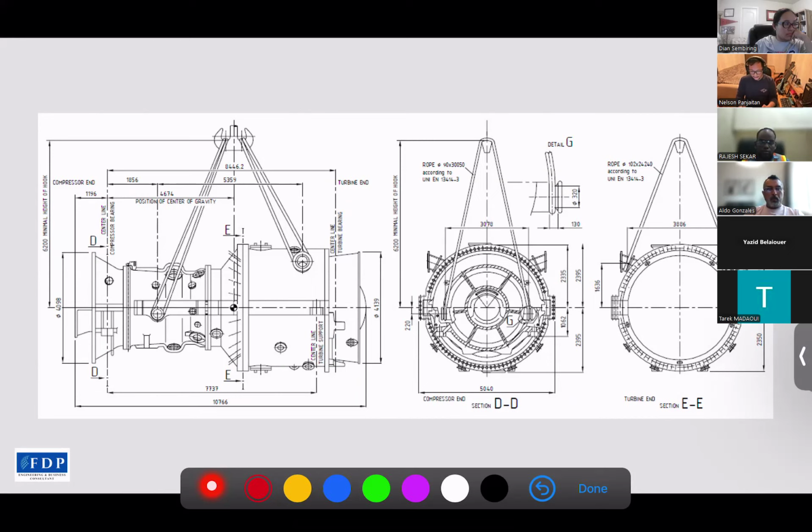we need to lift this turbine to the yard, and you can choose either it's a single crane or double crane. But for information here, we will limit the UC maximum up to 80%. And you are free to choose whatever crane will be used as long as you have the crane data. And if you don't have any, you can just tell me so I could provide some cranes including the information. And that would be better if you could get the ground bearing pressure as well.